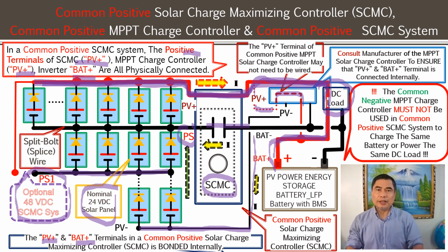Also, another way is to check the manufacturer's manual for how they suggest this system be connected. If PV positive and battery positive are connected and bonded somewhere, in the same terminal block, then you say, okay, this is 100% for sure a common positive design.